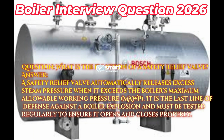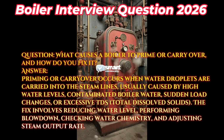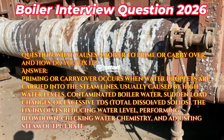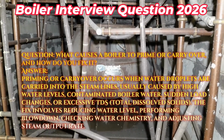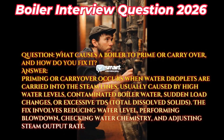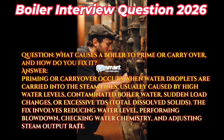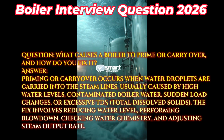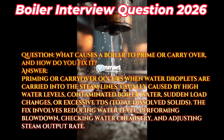Question: what causes a boiler to prime or carry over, and how do you fix it? Answer: priming or carryover occurs when water droplets are carried into the steam lines, usually caused by high water levels, contaminated boiler water, sudden load changes, or excessive TDS, total dissolved solids. The fix involves reducing water level, performing blowdown, checking water chemistry, and adjusting steam output rate.